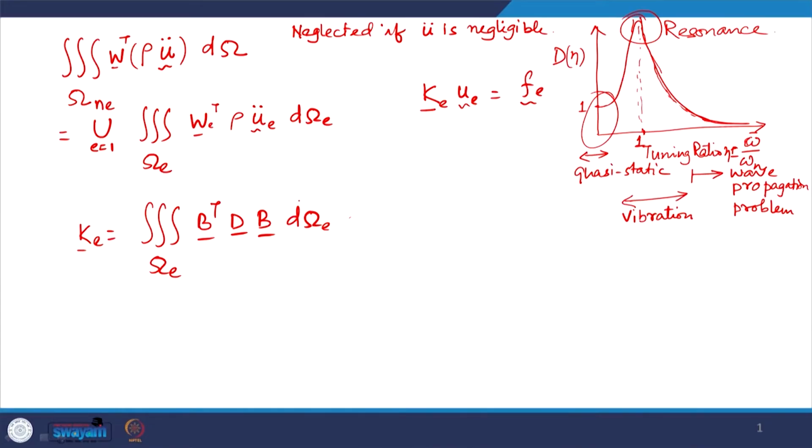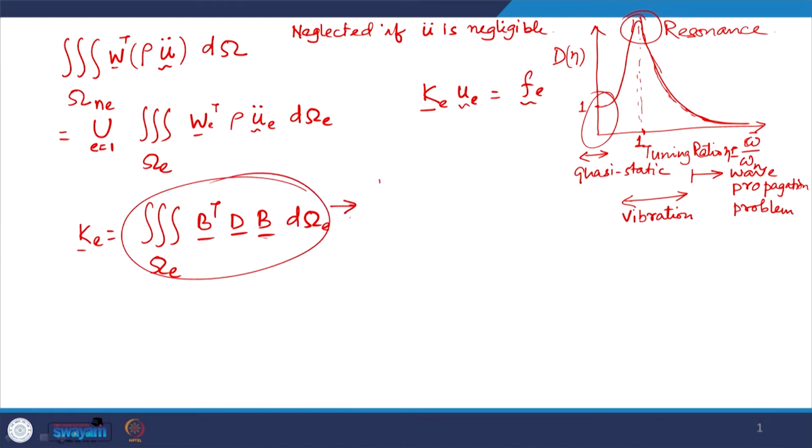that are applied on the structure or the element. So, this single vector includes contributions coming from body forces as well as from surface traction, if the element boundary coincides with the problem boundary, the domain boundary. All these, the strain displacement matrix, are of course based on interpolation of displacement, how we interpolate displacements. So, this is based on the field approximation